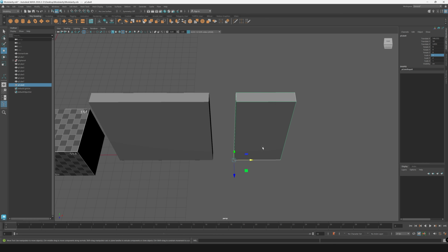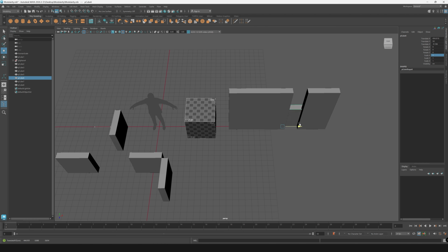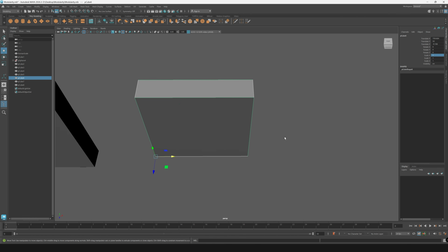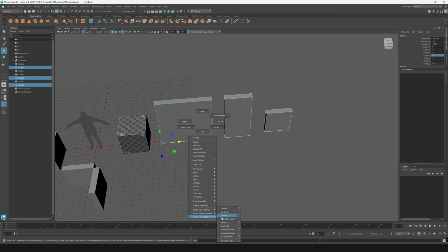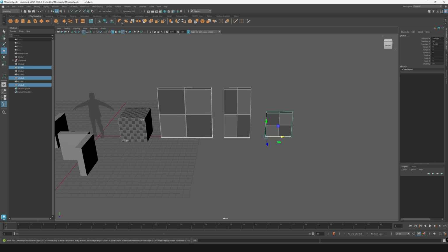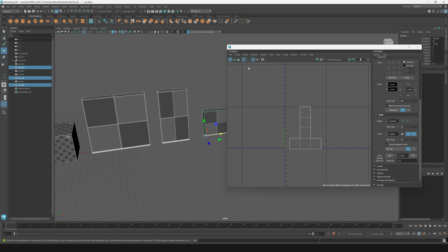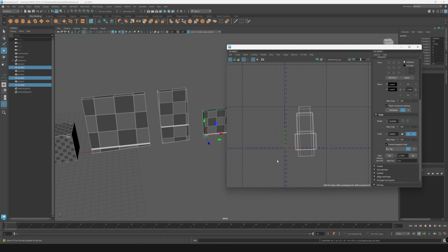The smart, good idea about this is that essentially, if we look at the textures on these guys, we want to make sure that they are seamless. Now, right now, texture-wise, there's nothing on them. So here, let me swap these textures to the texel density. But oh no, the texel density is wrong on every single one of them. So let's quickly go into each one of these guys and let's fix them. So the easiest thing is just going in here to modify and first doing an unfold so that it re-unfolds everything to the proper dimensions.